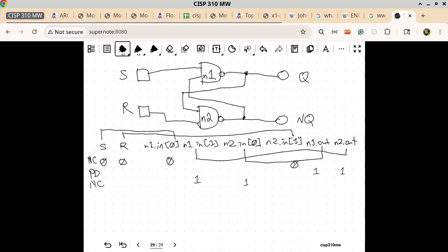Yes? That's just because of node connectivity. So now we go for another PD, because every time you change the input of something, you have to go for a PD. It's not going to change anything anymore because at this point, this input of 0 still guarantees the output is a 1. This input of 0 still guarantees the output of that one being a 1. So we have a steady state. So are we good so far with this analysis up to this point?